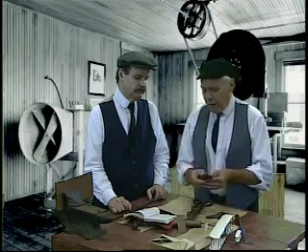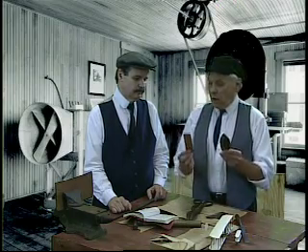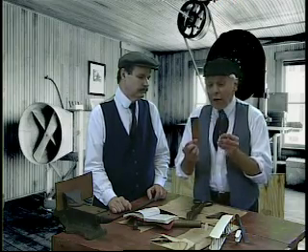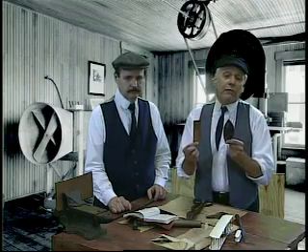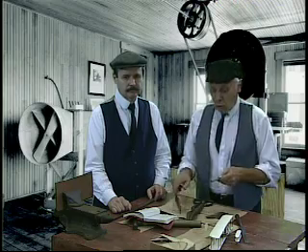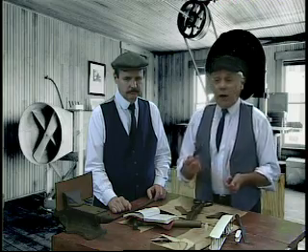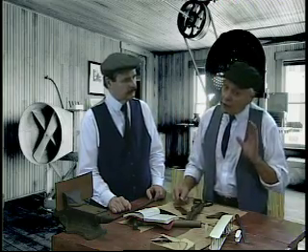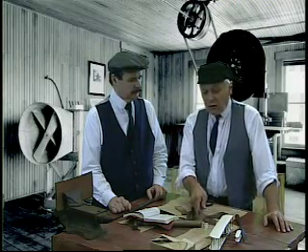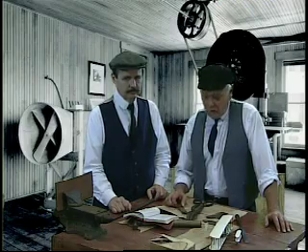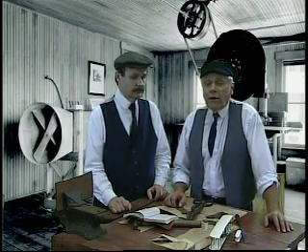Well, when we made a comparison between elliptical models and rectangular models, we found out that this shape has a big influence on the amount of lift and drag you get. We actually tested Lilienthal's model in our wind tunnel and found out that for his shape, he got his numbers pretty correct. His values of lift coefficients were right on.